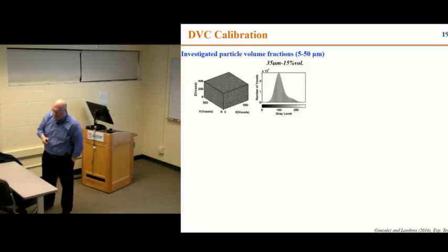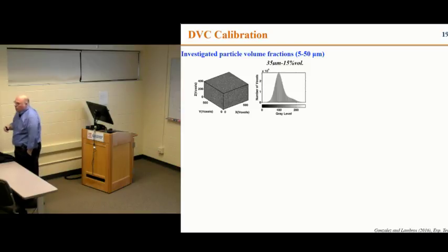Going back again to your question about the pattern, there's a lot of work that has to go in to get a pattern that will work. We make this work by doing a lot of studies to try and figure out what the best possible pattern is. We make the pattern because we seed the particles. Now, it may not be possible to do this in every material. And the same thing happens, of course, in 2D correlation as well, right? Sometimes we use natural features that occur in the material. If they're there and they can be used for image correlation, great. If there aren't, you have to put something in.